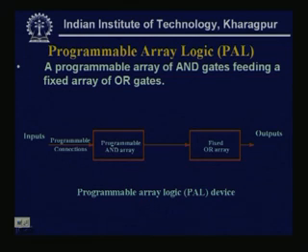See here, the AND array is programmable, so when the inputs go in, those can be programmable connections. This AND array can be programmed, but the OR array is fixed. So, this is called the PAL, programmable array logic.